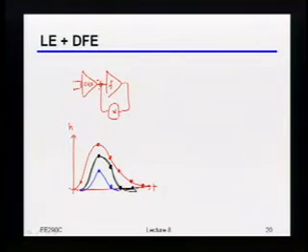Turns out a lot of times people will do these DFEs not because it's actually thermal noise that's really being amplified that causes a problem, but actually just because there's a lot of crosstalk that you might be picking up at the input of the CTLE. And so if you try and do everything with a linear equalizer, you'll amplify that crosstalk. Okay? So even just from that standpoint, oftentimes you'd want to do the DFE just so that your continuous time linear equalizer won't be peaking the crosstalk, right? Which really has nothing to do with thermal noise, but for the same reason that it peaks thermal noise, it also would peak crosstalk. Okay? Does that kind of make sense to people, or?